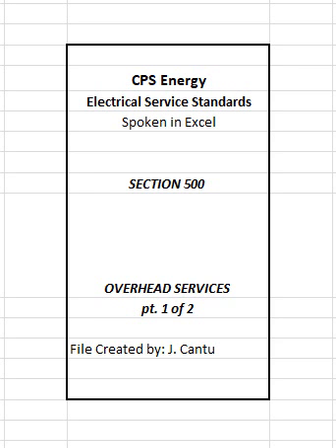Note: Customer shall coordinate with the CPS Energy customer service representative where temporary or permanent structures are to be constructed or placed under existing CPS Energy service drop conductors. Customer will be responsible for costs associated with clearance poles if minimum requirements of Figure 501 are not maintained.